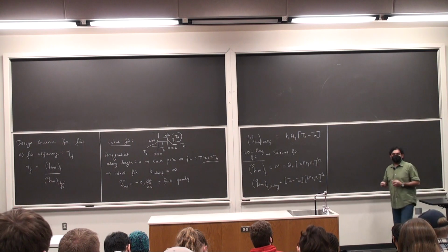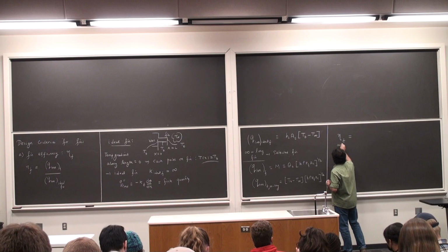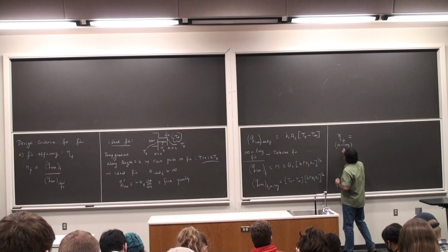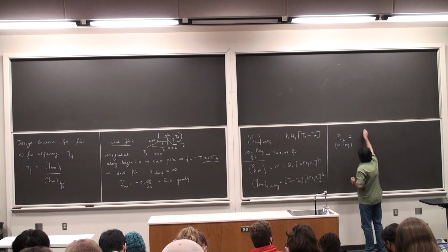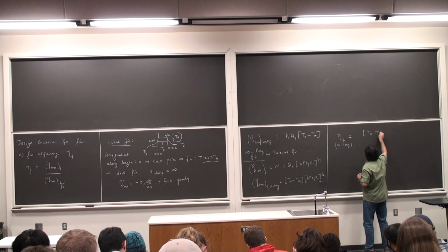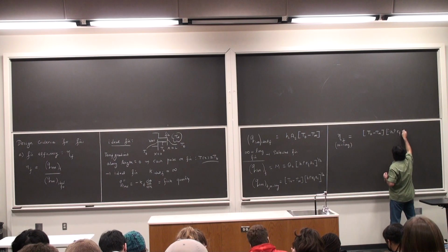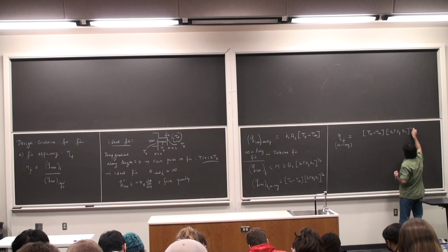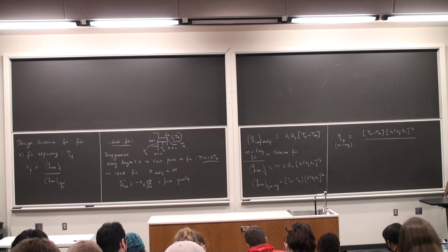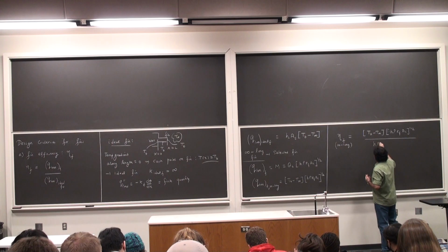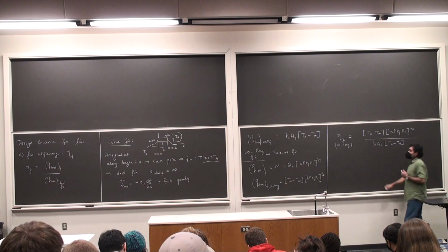Let's see what the efficiency is going to be. Okay, so this is for an infinitely long situation. I just divide one by the other. So take the bottom one. This is Tb minus T infinity, h P Kf Ac divided by h times the surface area, remember, Tb minus T infinity.